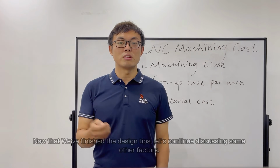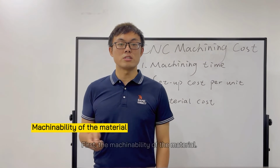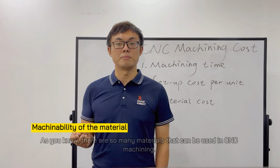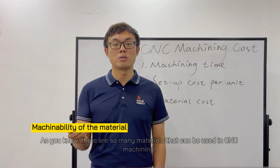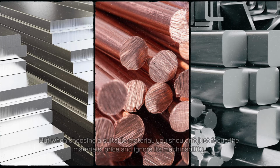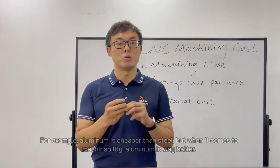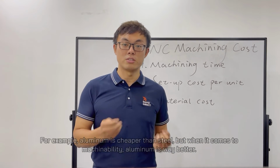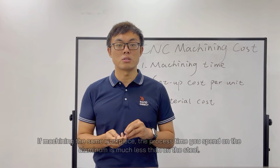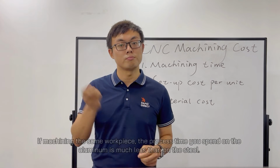Now that we've finished the design tips, let's continue discussing some other factors. First, the machinability of the material. As you know, there are so many materials that can be used in CNC machining. But when choosing a suitable material, you shouldn't just focus on the material's price and ignore its machinability. For example, aluminum is way cheaper than steel, but when it comes to machinability, aluminum is way better. In machining the same workpiece, the process time you spend on aluminum is much less than on steel.